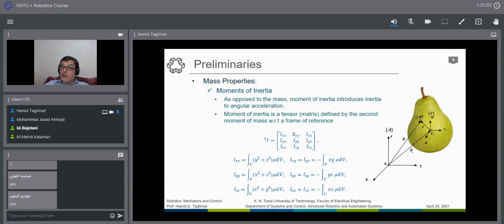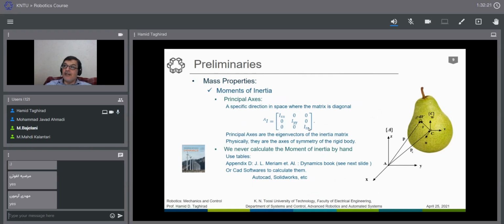And if you just use the homogeneous transformation, we can show that there is a completely particular frame. Here the frame is outside of the system. If we can bring the frame somehow within the system, so that the system becomes symmetric about it, then the moment of inertia becomes symmetric. The off-diagonal terms become zero, and the diagonal terms are all positive because we have positive mass.